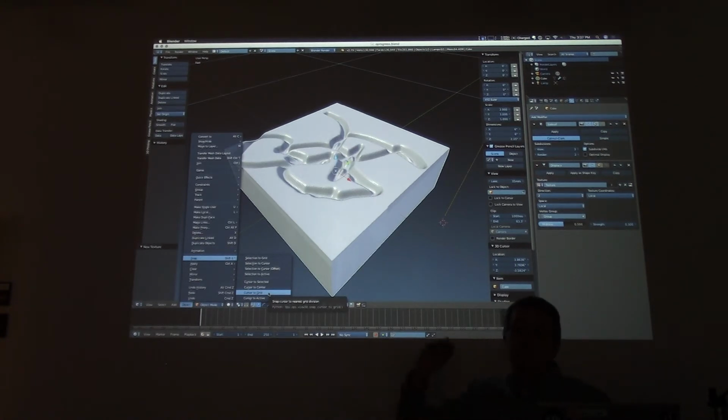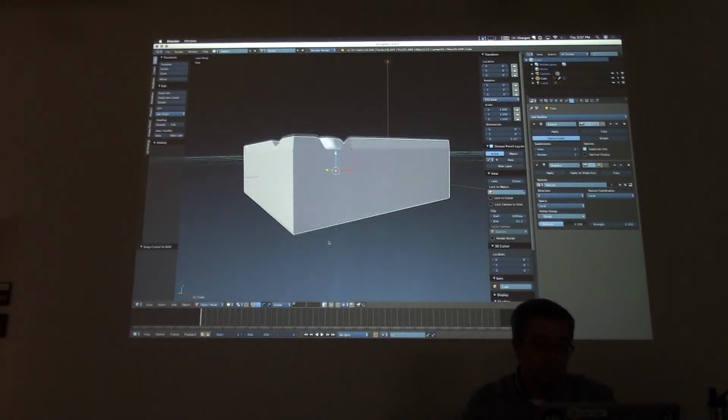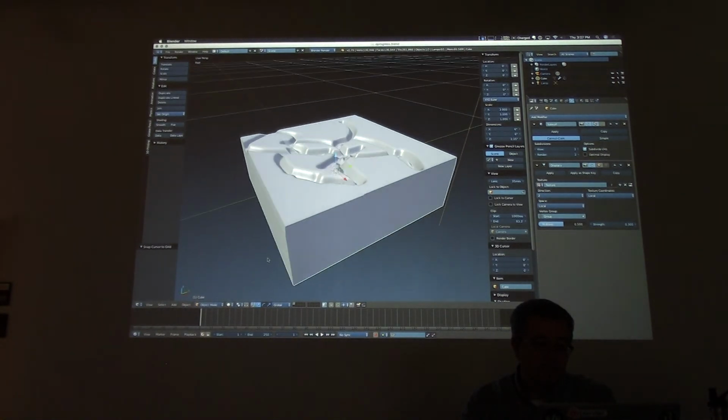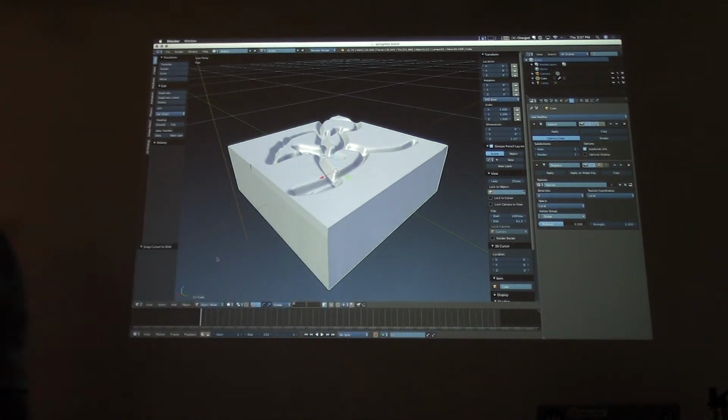So this basically says move that 3D cursor to my little crosshairs where my X, Y and Z axes come together. It didn't do it. It'll look like it's sort of on top of the object. It actually picked a different spot along the green axis that's not where all three come together. Is it cursor to grid? Yeah, I'll try it again. Object, snap. Yeah, it came over here.